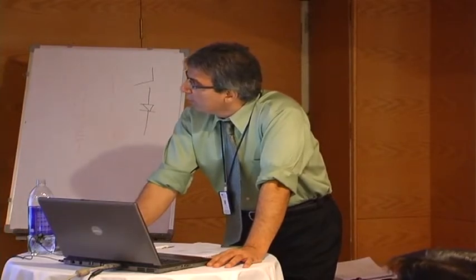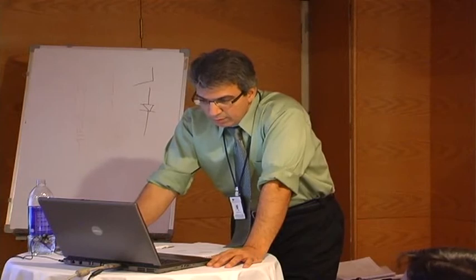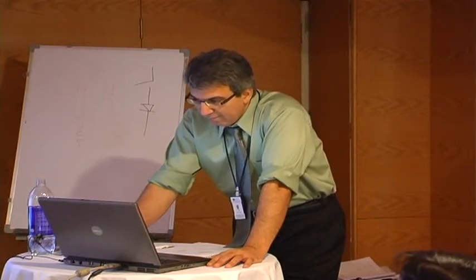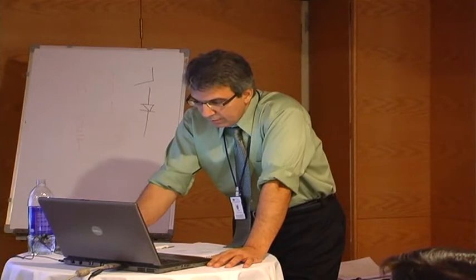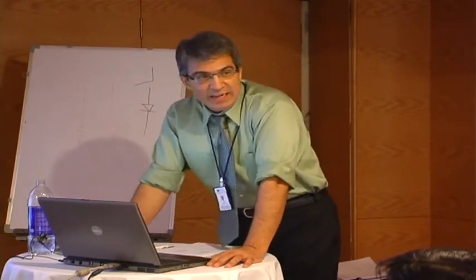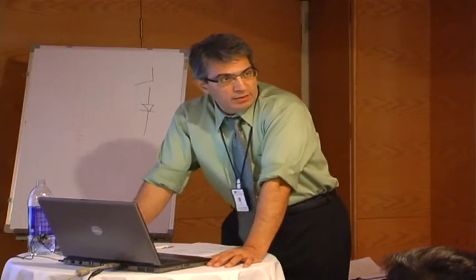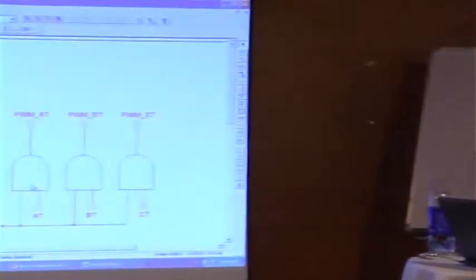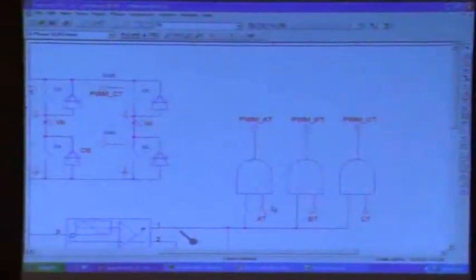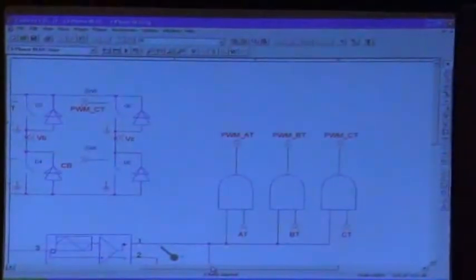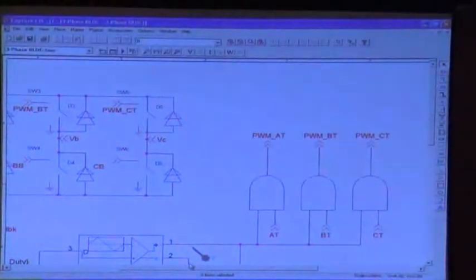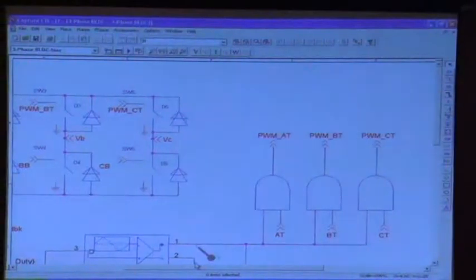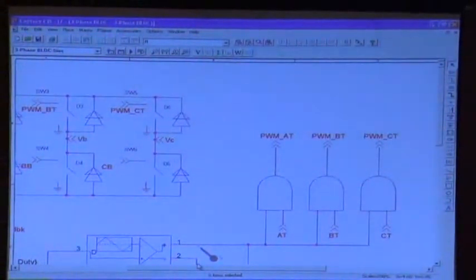All right. So this is what we have now. This is page 1 of the schematic. Now, using AND gates is not the smartest thing here. You can also use simple switches, so the switches turn on when you get a command, because the AND gate turns on the digital simulation part of PSpice, and the simulation is much better if you don't have to use the digital part of PSpice.